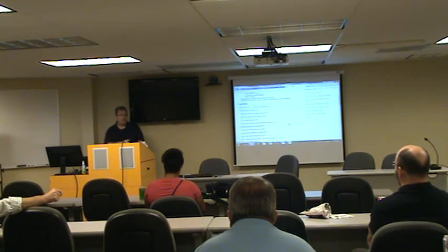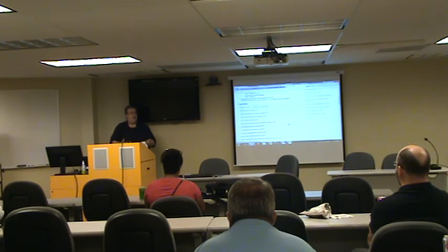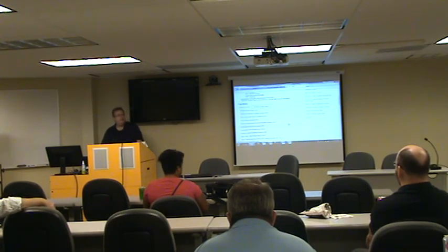So I have to have accountability back to how that drawing was made so I can update the model, print out the sheet, print out the PDF and send it over for archiving. How can I do that if I just get an IFC model and there's no structure of how that sheet was cut, what visibility settings were on, how the family, you get geometry, you don't get your families, you don't get anything else in there.